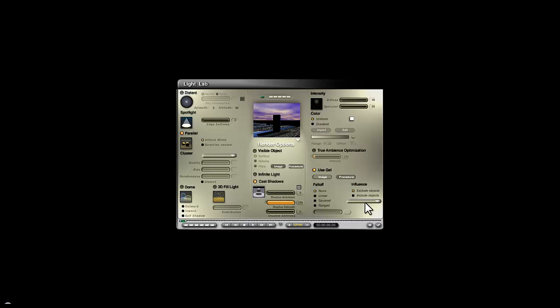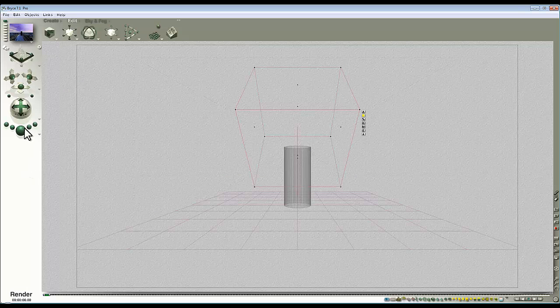Likewise we're going to struggle with reflection map to get anything reasonable, but things like object space is going to work for you, and parametric probably, yes, because it relates to the square shape. So a few things to experiment with there, and essentially parametric or object space is going to be your choice if you're going to be trying to project caustics onto the surface.